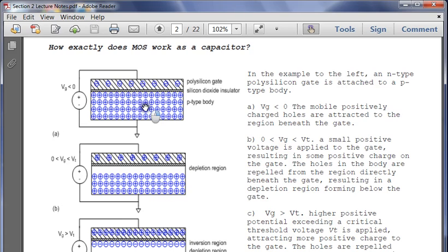But now we apply a voltage in the second stage, below what's known as the threshold voltage. So we have increased it. Now we're starting to bring the positive carriers up and away, because we're attracting the negative carriers. Likewise, the positive dopants start being dragged down because they're going towards the negative voltage here. So what you're creating is what's known as the depletion region.